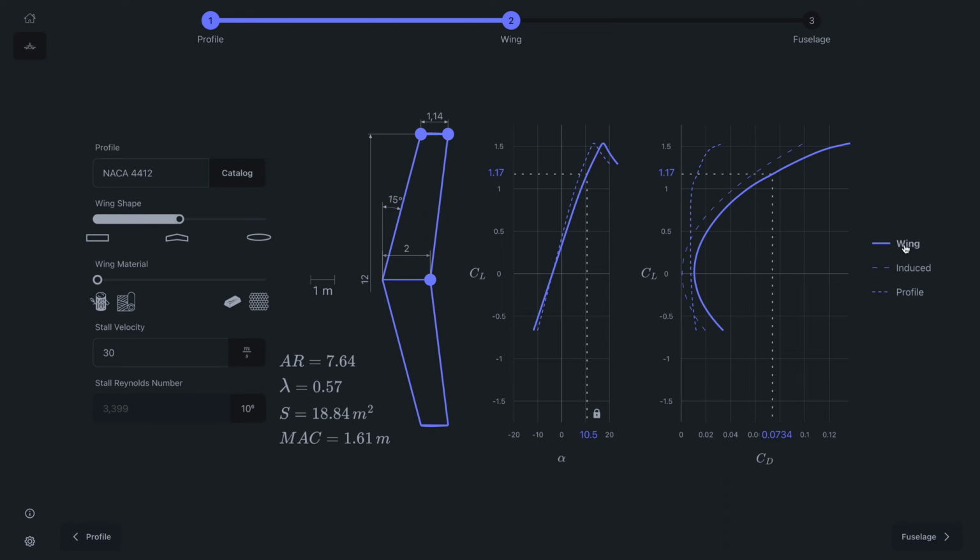It's worth noting how big of an impact induced drag has on a wing. For a typical jetliner at cruise speed, it can account for around 40% of total drag. Nowadays, aircraft designers employ innovative aerodynamic solutions like winglets to enhance overall efficiency. They use super fast computers to simulate the flow and extract every little bit of performance from the plane. But let's not get ahead of ourselves and start with choosing the shape.